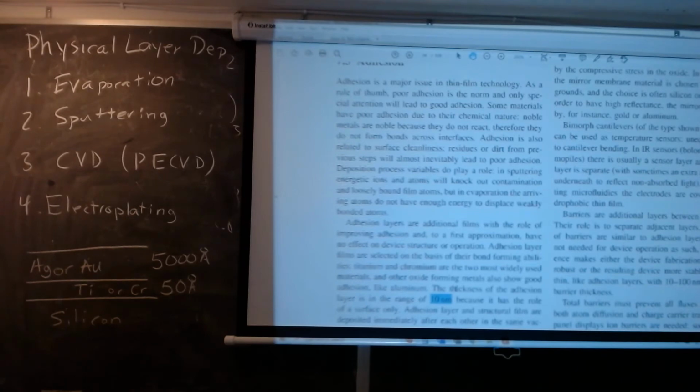If you deposit 5 microns of gold, you're going through, you know, $1,000 worth of gold. Whereas if you can do it with silver, silver is roughly, these days, 1% of the cost of gold. Silver goes for $20 an ounce, whereas gold can go for $2,000 an ounce.